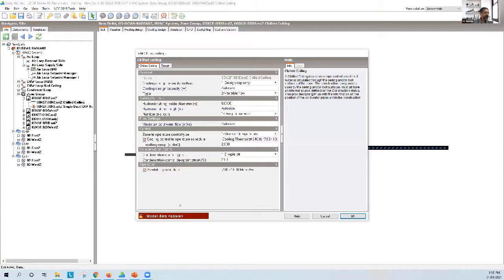Okay. Now, I have turned on condensation control because you've got to manage condensation. And what I've said is that when the internal temperatures get to within 2 degrees of the dew point, then start switching off the internal beams, the radiant ceiling. But if you don't do that, then you will get condensation on the ceiling.